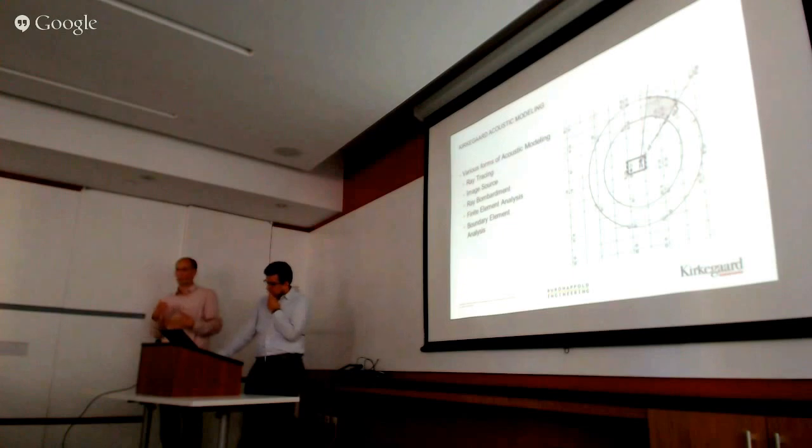So usually we'll set up this solution to recreate the early sound because it is so accurate, and you're not going to miss a reflection from a major surface between a source and a receiver. But as you increase the mathematical order of the image source solution, it explodes. So much beyond 3 orders, it's really not computationally efficient to run a model that way.